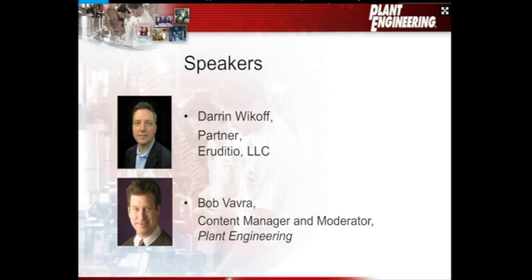One of the things we talk about with readers when I'm out in facilities is making sure that their spares are stocked appropriately to their more immediate needs. You don't want to have 6 motors sitting on the shelf if your motors only go out once every 2 or 3 years. You've just paid for a whole lot of assets that you can't get any return on. So as I'm learning about this, we're talking about asset management as a process as opposed to maintenance, which tends to be an event.